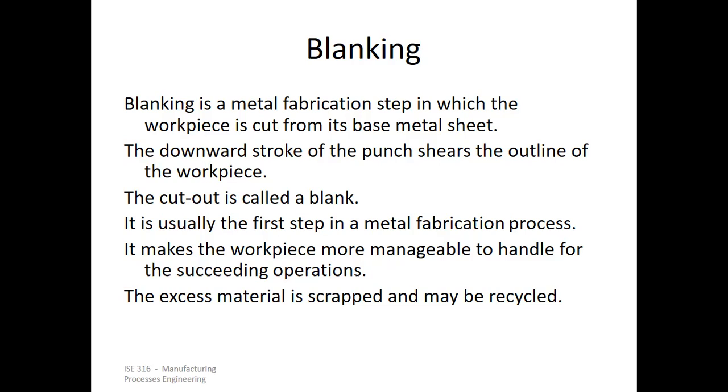So this is why we are calling it the first step, and it makes the workpiece more manageable to handle for succeeding operations, as we know. We can't just move that strip to every place. What we can do is take out a card from that strip, decide the profile accordingly, and then that profile which you've taken out will be sent to succeeding operations.